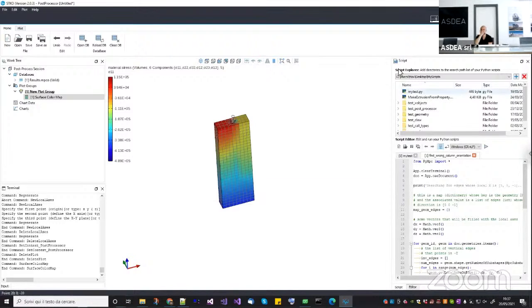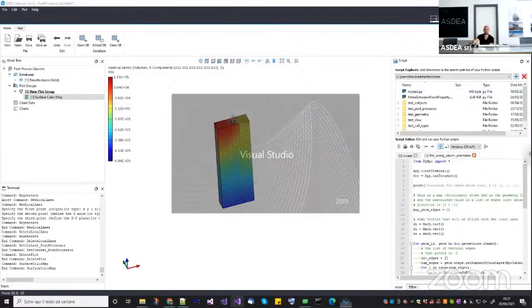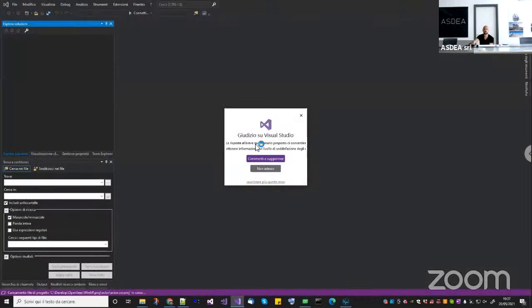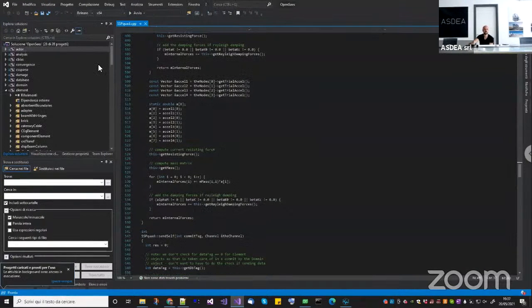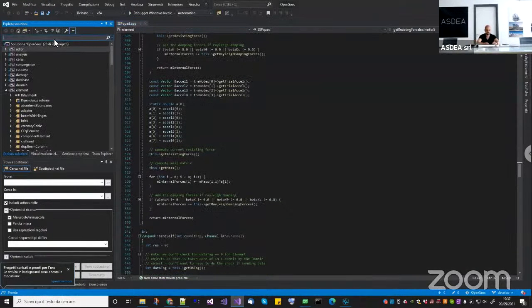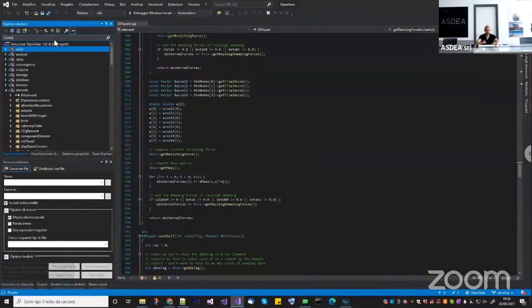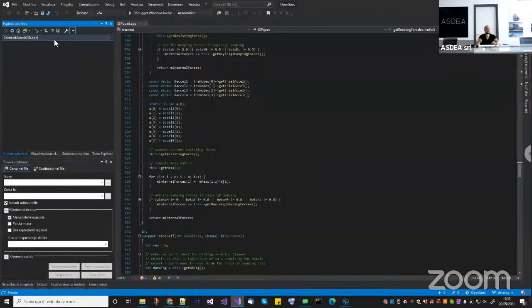For clays and solid soil, it can be important at the contact. Yeah, the problem is that I don't know if you can change it. Actually, let me look inside the source code, because probably you can change the cohesion using the set parameter. Okay, so let me just have a look at the contact material 3D, C++.